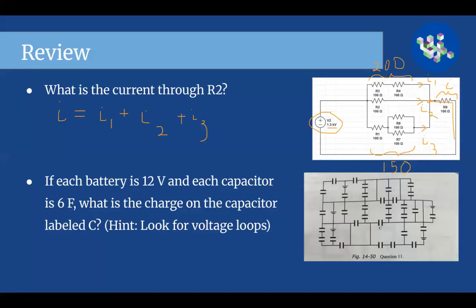You can find I from your V and the overall resistance. So we know I, and we also know the voltage. Using I, we can do V minus I times R9, where R9 is this resistor, to get the voltage across the parallel section.